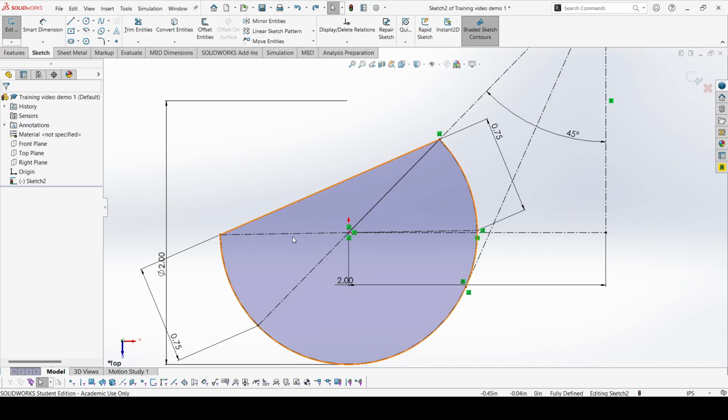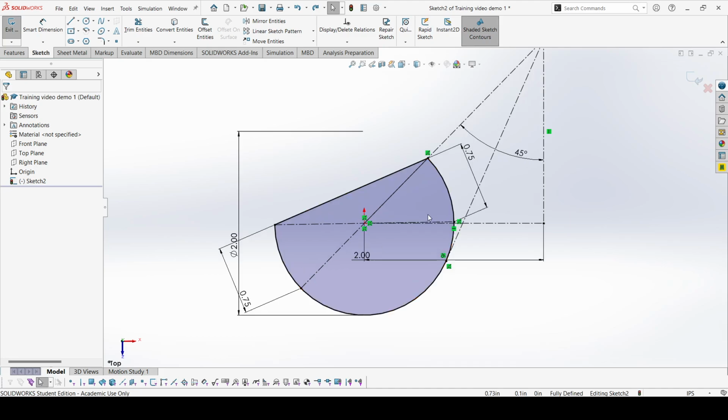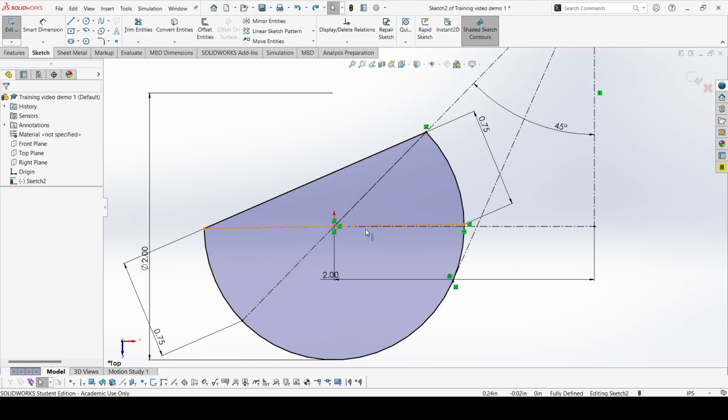And you'll notice now this whole thing is filled in one color. Earlier, when I cut that, this turned white, but before it was blue, and where the rectangle was, it was a darker blue. That's because they were two separate contours. If I do something like that, either one contour is going to cut through the other, or if I've got contours intersecting like a Venn diagram, I'm going to get an issue that requires me to use selected contours, which is not something we want to do.